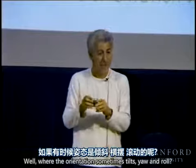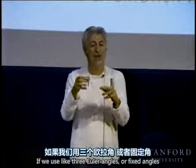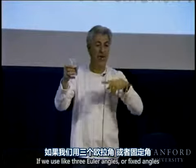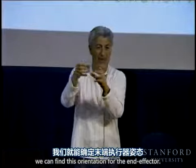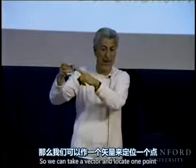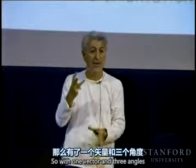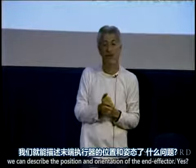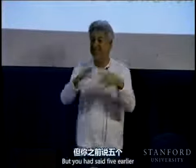Well, for the orientation, sometimes yaw and roll. Okay, you use 3 angles. So if we use like 3 Euler angles or fixed angles, we can find this position orientation for the end effector. And for the position, x, y, and z. So we can take a vector and locate one point, fixed point. So with one vector and 3 angles, we can describe the position and orientation of the end effector. Yes? Isn't that 6 parameters? Perfect. 6 parameters.